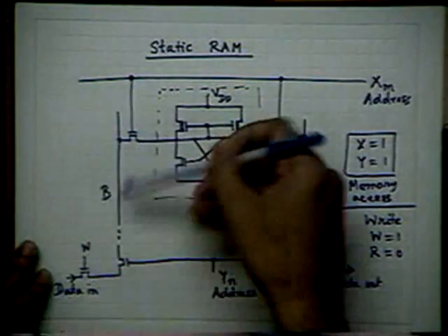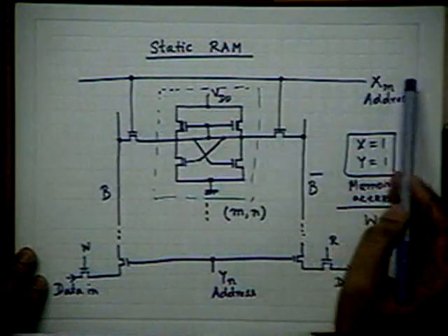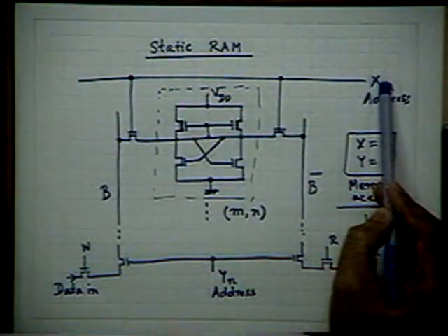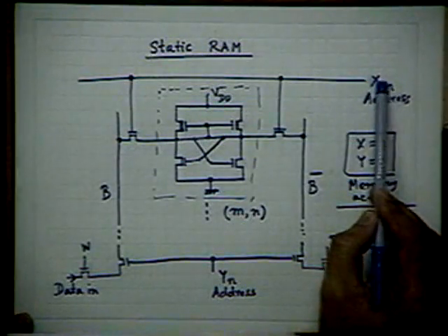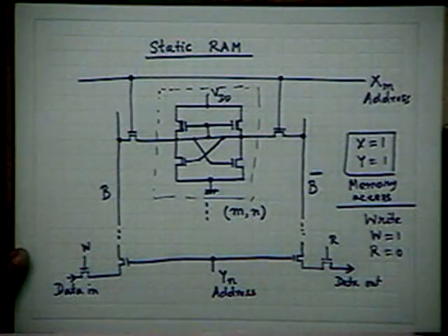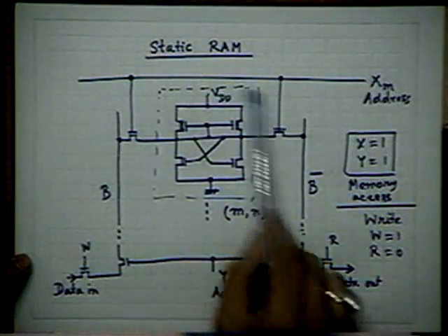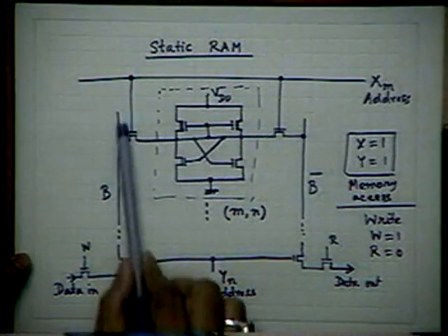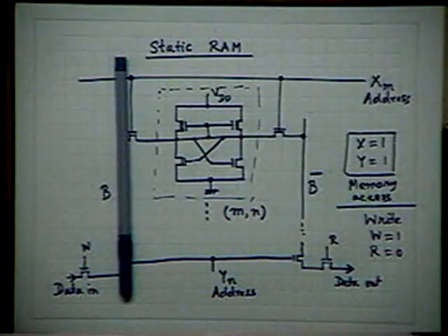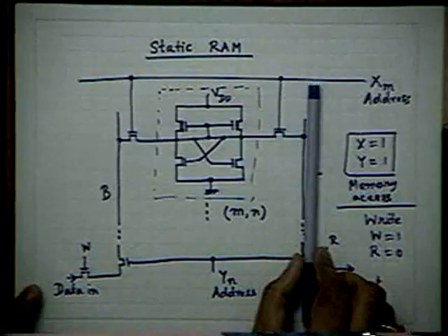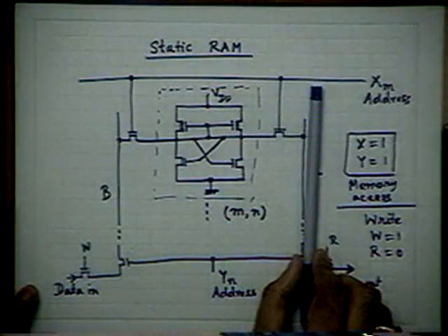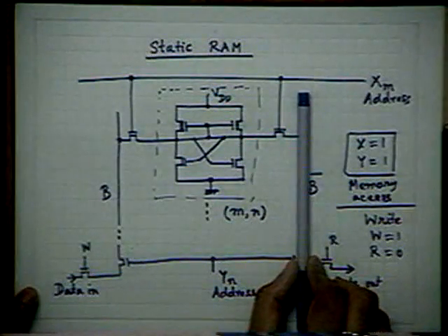Suppose all these transistors are off. All X's are 0. X1, X2, etc. All of them I have kept 0. Therefore, these circuits are not coming into the picture. But the bit line itself is floating on an oxide, on silicon. And there is MOS capacitance, as well as junction capacitance. So each bit line will have substantial capacitance.